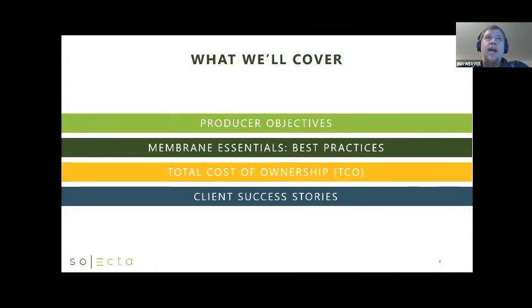And then we're going to tie that to total cost of ownership. As I mentioned, we want to look at process economics to make the best decisions. And when we're talking about either an automotive plant or a large parts coating line, the UF can just seem like a small cog, and typically can be replaced based on, the flow rate's too low, let's just replace the element. But we want to take it to the next level and really monitor and use data to provide the optimal time to replace elements from a process economics perspective.